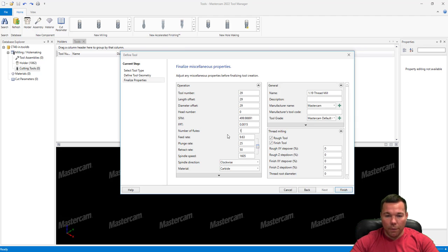It is a one flute tool. So we're taking about 2.5 thousandths per chip per tooth. We have one flute. We're running a 500 surface foot, so our feed rate generally is about 4 inches a minute on this. Of course, this is in steel.